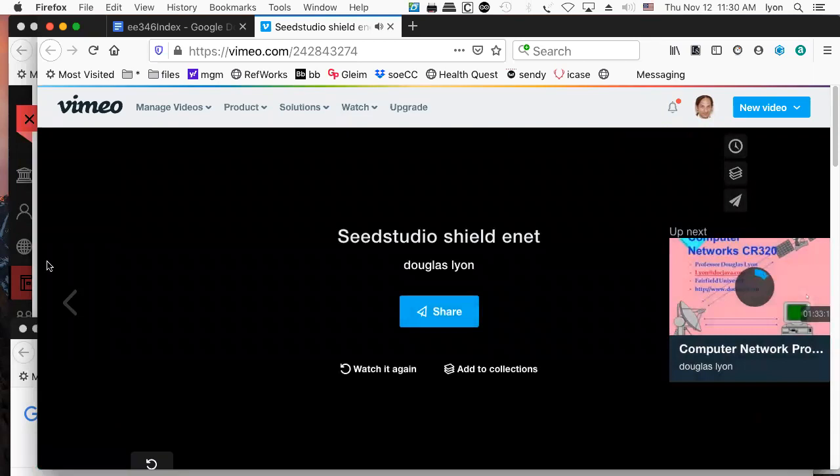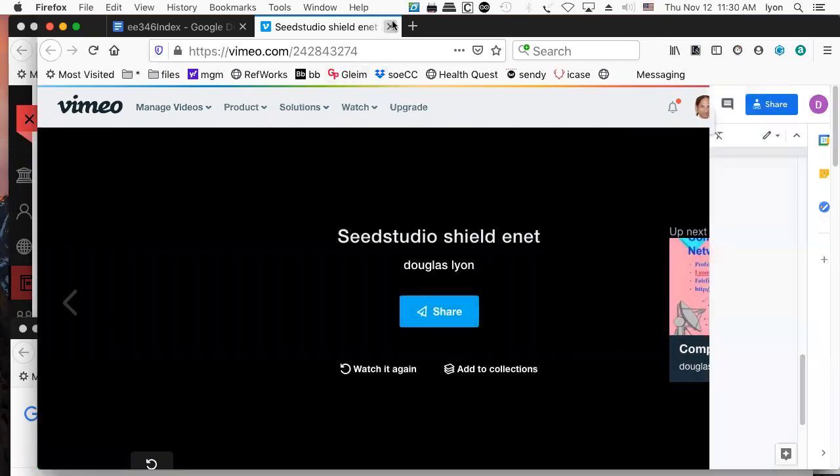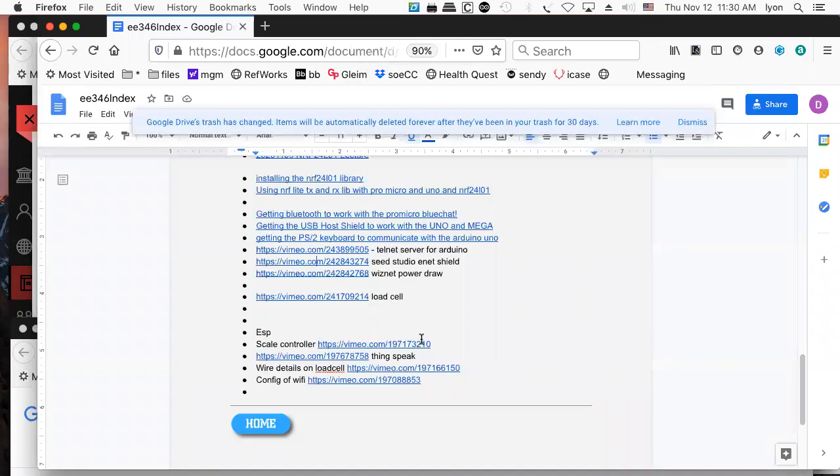So therein lies a warning. If you try and plug these things in without any kind of power assistance, they draw so much power they can basically take down your USB hub. A lot of times we take for granted that we can power our Arduinos off of the USB from our laptops. Oftentimes during a debug session, I'll plug in an adapter because I'm afraid we overloaded the USB output from somebody's laptop and things don't work properly because of the power issues.